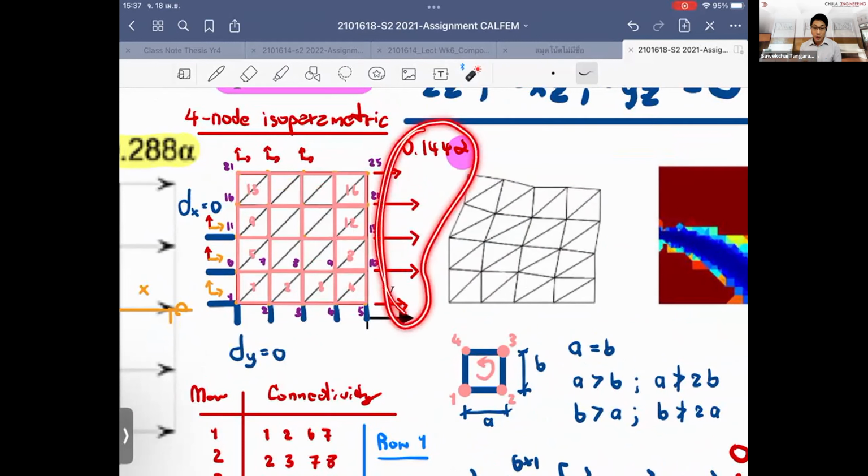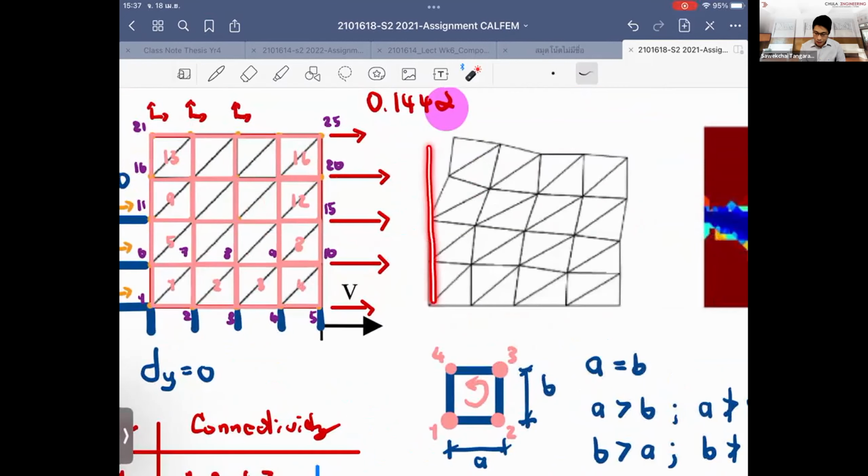This is a function of the applied external force, which is F or P. Right, when there is a force applied here and you have the restraint condition at this direction here, you're seeing that along the boundary line, it doesn't move or translate in the X direction at all, because we fix them, but it can move in Y. But along these directions here, it doesn't move in Y, but it can translate, so it can slide, right? Except the node here in the X direction. This is the deformed shape of what we expect to see.